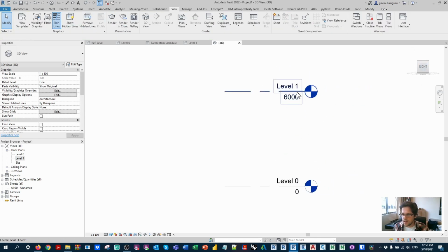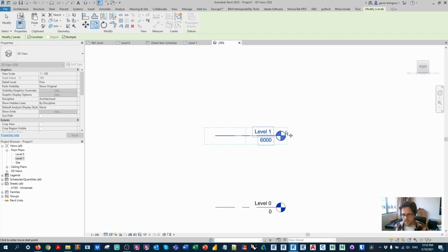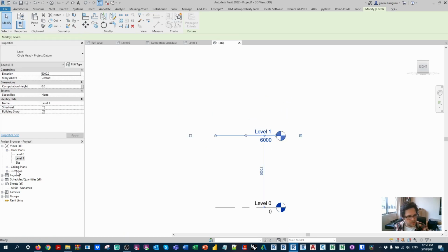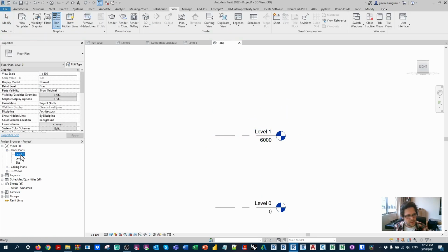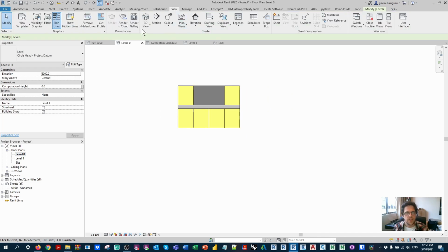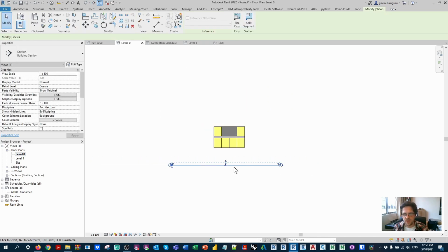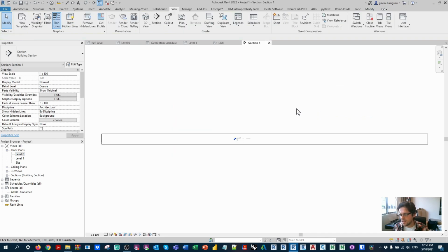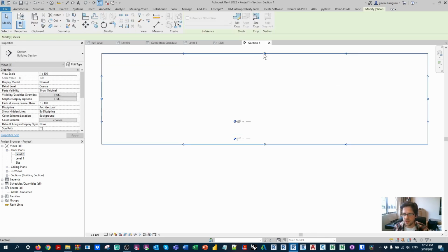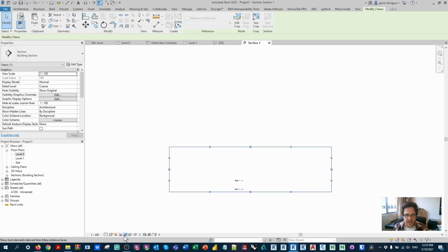And then I'm just going to start making a few extra floors. Might go to an elevation. Actually, I need to create one, because we're just going to make some more floors. Now, the reason why massing is a little bit challenging is because you're sort of depending on levels to generate your outcome.